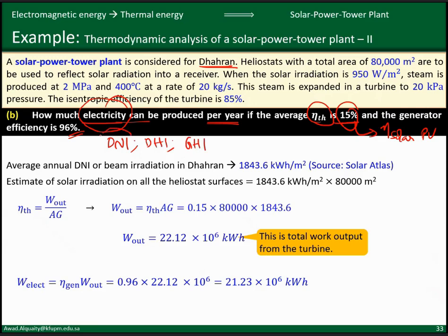When we talk about concentrated solar devices, which make use of beam radiation, we have to use DNI, because it's the direct radiation from the sun that is converted to more useful forms of energy. So for all concentrated solar systems, we have to make use of DNI to scale our system and calculate its energy output.